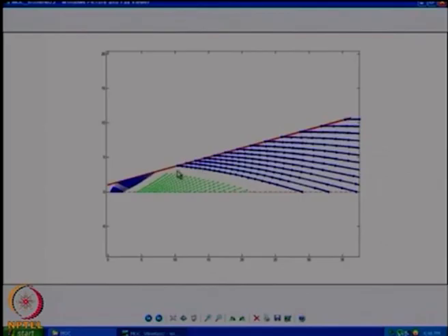This is how I can show it to you much more clearly here. Till now, I was solving left running characteristics from here, and suddenly I switched to right running characteristics. The reason will be more obvious in the next picture. I wanted to study the flow around the center of the nozzle, not what is happening at the boundary. That is not what I was interested in. I was interested in what is happening in the center line. So I wanted to go for right running characteristics. Yeah, I talked about this already.